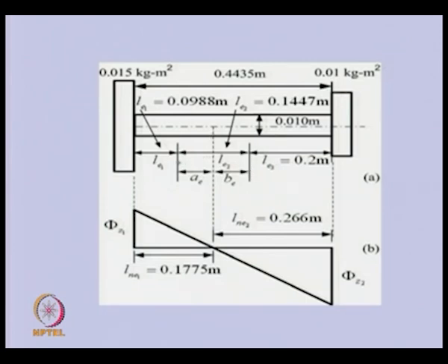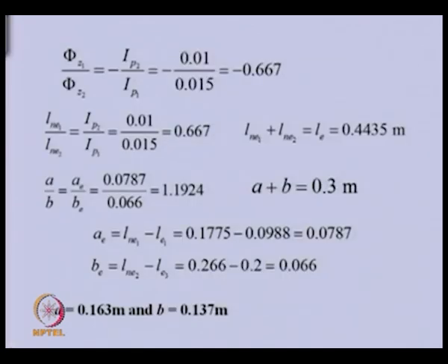So from, let us say, this end, the position of the node is AE, and from this end it is BE. So this ratio, as we have seen in the analysis, now we know this ratio. In the original system, the node location will be proportional to this equivalent shaft system.